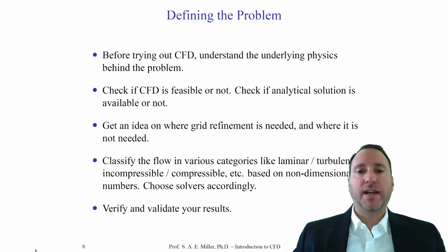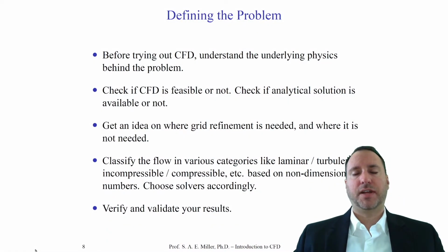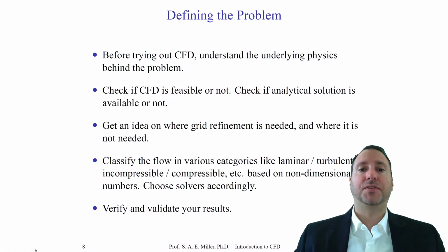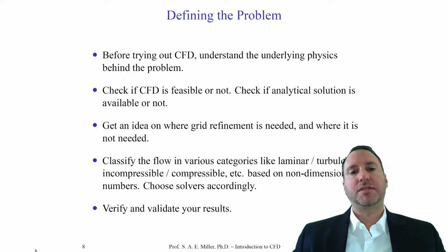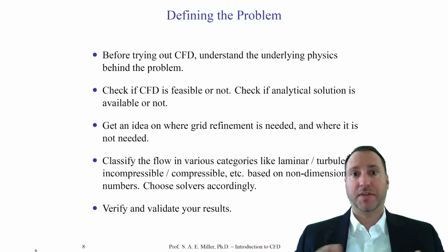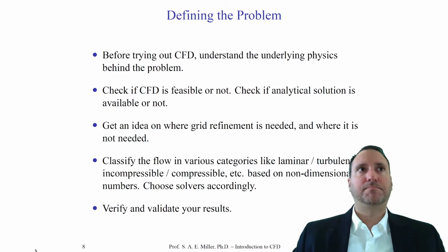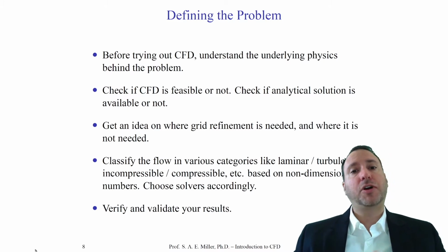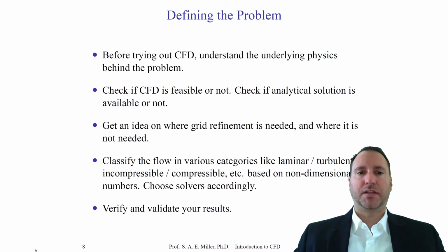Before you even do CFD, think about if it's the appropriate tool, because today, for engineering design, CFD is one of many, many tools. So check if an analytical solution exists for your case or not. It is most likely not available. Or maybe there's some other method that is more appropriate to study the problem. Perhaps it's just better to go into a wind tunnel and do an experiment, if that's even feasible. Perhaps it's easier to look up literature. Maybe other people have studied the problem.